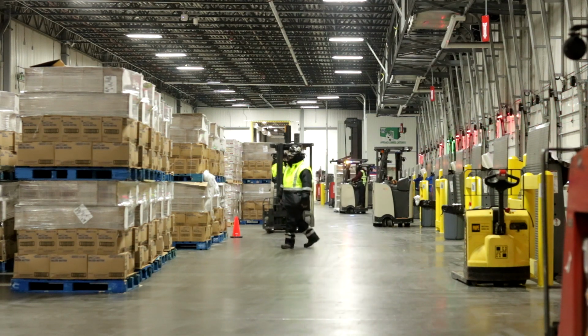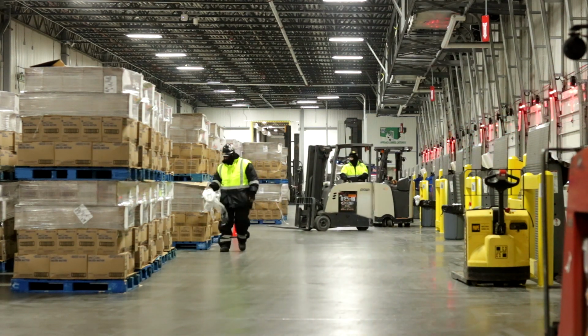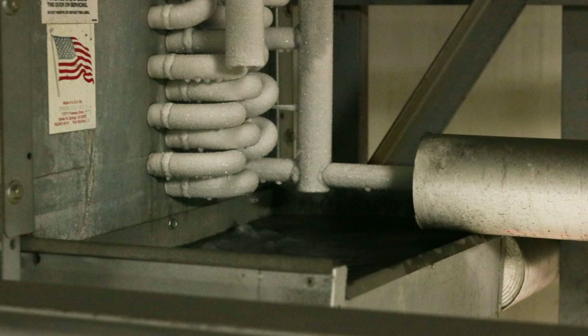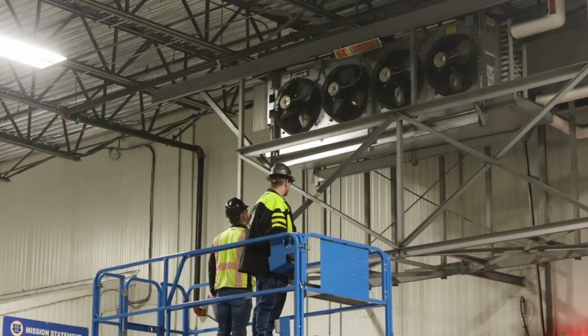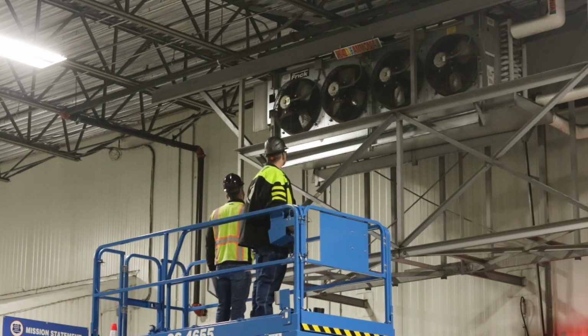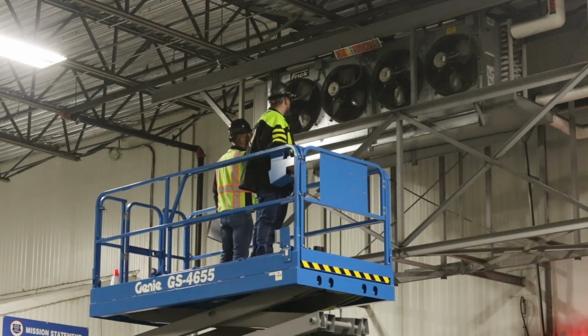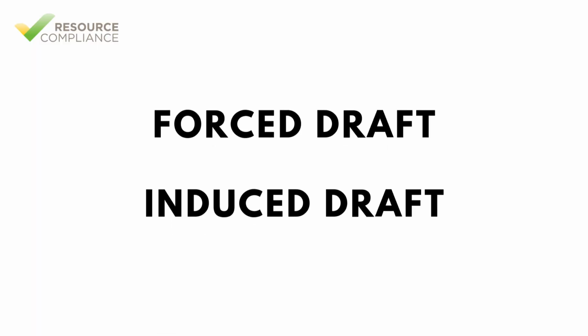Often, air cooling evaporators are packaged within an enclosure which includes fin tubes, 1 or more fans, and a drain pan to collect water that condenses on the coil's surface. These evaporator units come with connections so that liquid, vapor, and defrost pipes can be directly connected to the evaporator. Air cooling evaporators are categorized as forced draft or induced draft.